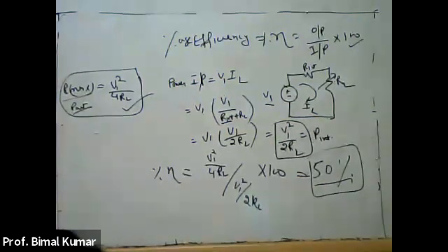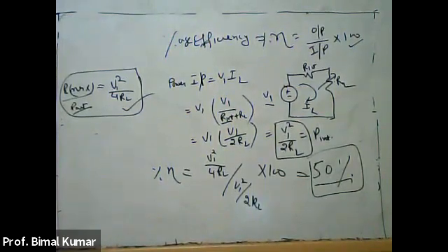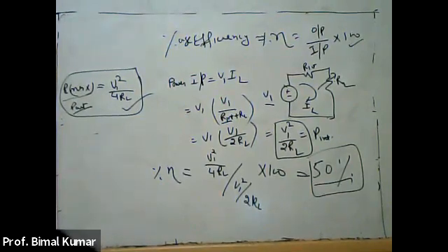So by substituting both of those values, you will be able to calculate maximum power as per the maximum power transfer theorem. That means you must be able to calculate VTH and RTH by the use of Thevenin theorem if we want to calculate maximum power transfer across the load as per the maximum power transfer theorem, right? So this is regarding the various steps for calculating the maximum power transfer across the load resistance.